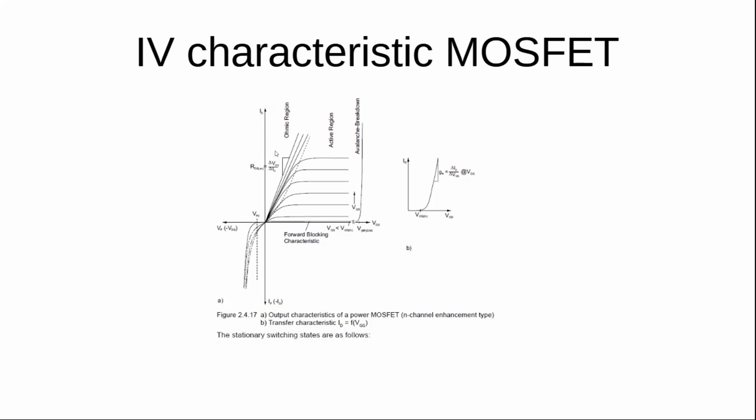So that's the situation. Then, as we said, we can also have this negative part because we have a body diode in there. But it's a PN diode, so it's going to be slower. It's a bipolar diode, so it'll be a bit slow. Then, of course, you have the usual limits. If the VDS is too big, then this device will break, meaning that there's a limit to how large a voltage you can block.